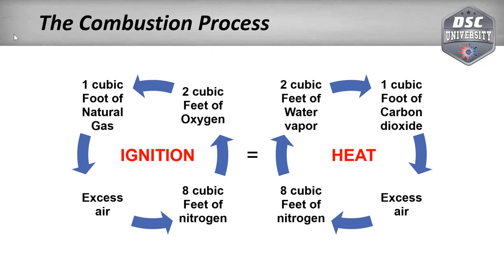The reason that would happen is if the burners are dirty, or if the flames are hitting up against the metal, it'll cause incomplete combustion. If the furnace is overfired and the flames are too big, there's a lot of different things. The main one is not having enough air coming into the furnace, so it doesn't have enough oxygen to burn, so instead of producing carbon dioxide, it starts producing carbon monoxide, and then that's when it becomes dangerous.